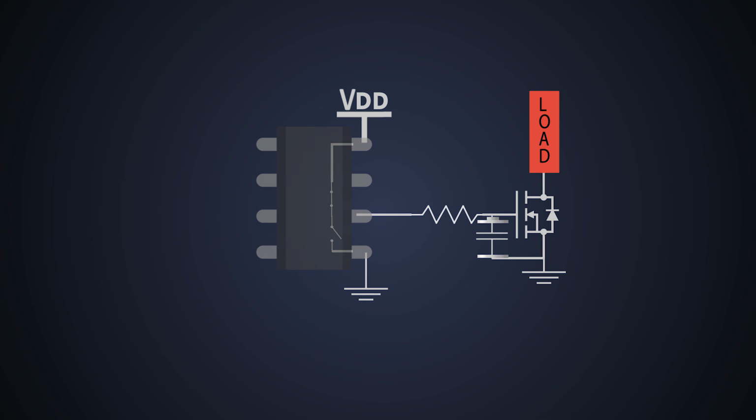When we use the driver circuitry to turn on the power MOSFET, a certain charge has to be supplied to the gate to raise it to the desired voltage level. The large power MOSFET has higher gate capacitance. So, the gate driver acts as a voltage source capable of supplying the right amount of current in the shortest possible time, which charges the input capacitor.